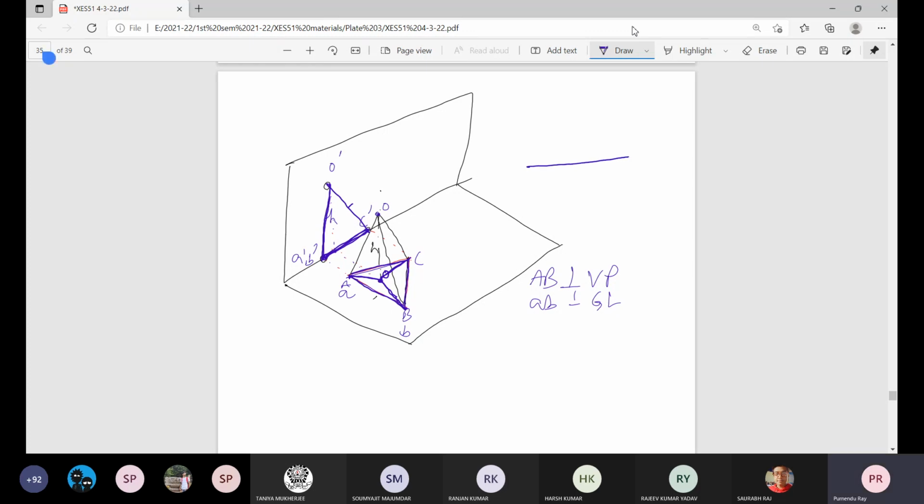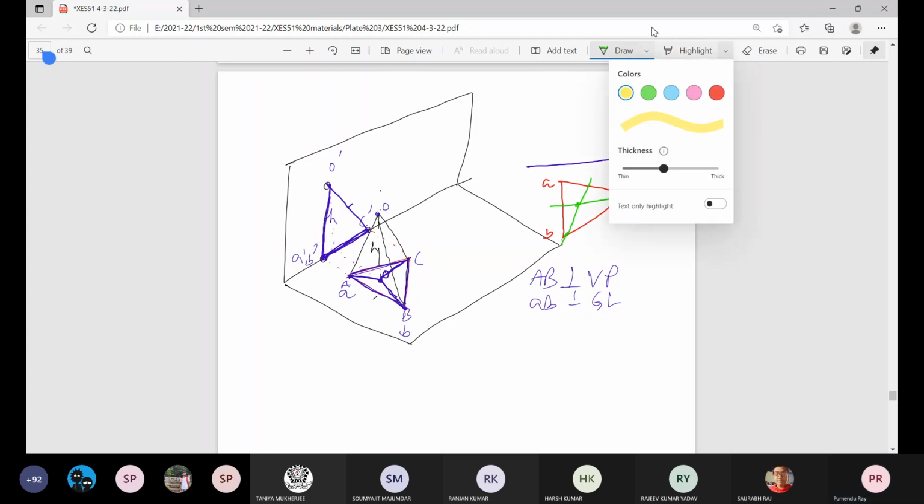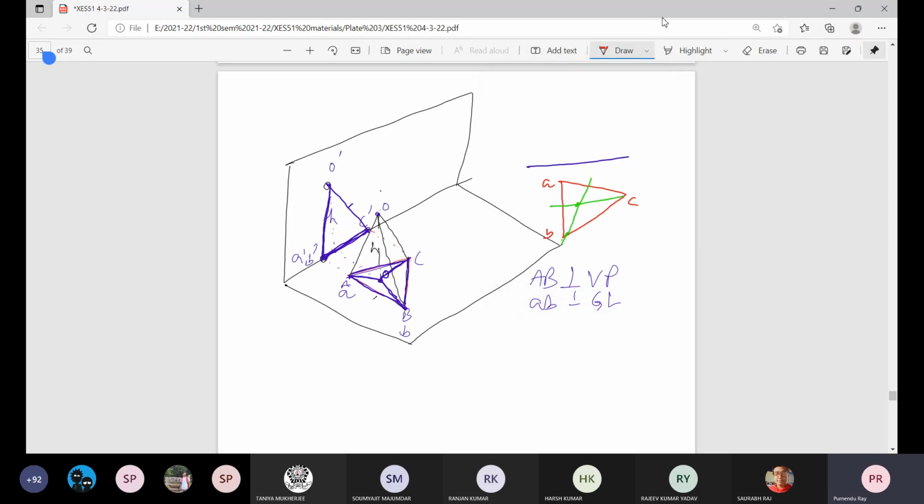So finally, when we work on this formal 2D presentation of the projection of a simple solid, we will draw the ground line, then draw the base figure, that is the triangle of given side. Find its geometrical center by simply drawing these medians. This is the geometrical center. It will be the plan of that apex.